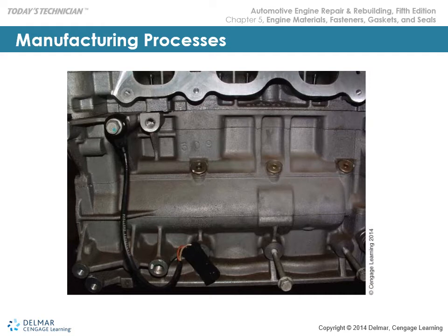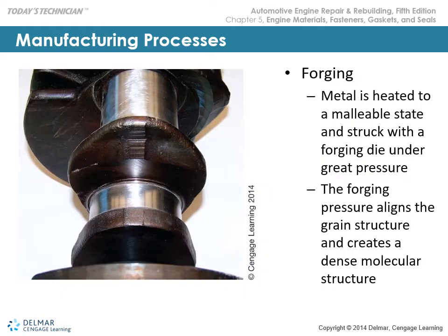Okay, this manufacturing process is showing the side view of an engine block. Okay, forging. Forging actually takes the metal and pressurizes it and comes up with what's called a near net shape, so that only a small percentage of material is removed.